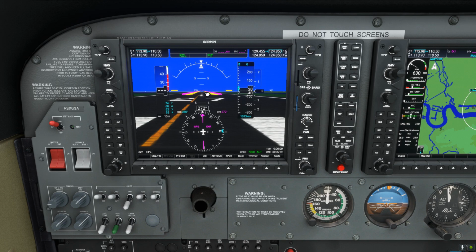So basically, it's a guidance indicator, and in something like the airliners, so the 146, A320, 737, the flight director will show differently. If you were to program certain routes into your flight management system in the airliners, then the flight director will be showing you what gradient you should be pitching at and turning to follow the course.